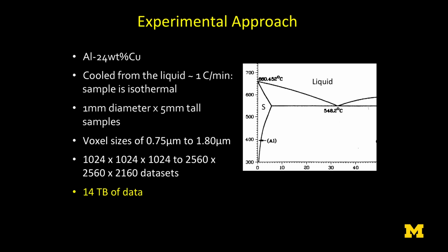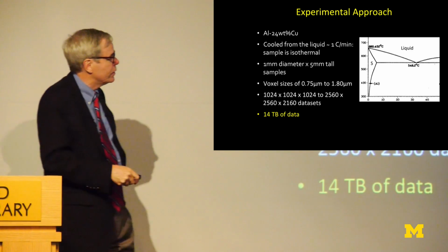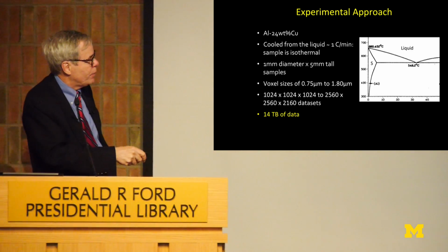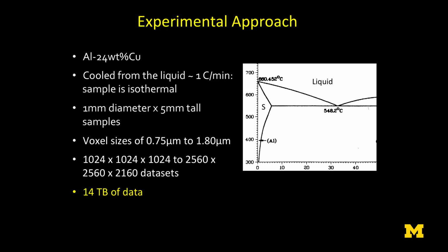So here's the experiment. We start with a liquid up here, solid over here, solid down here. This is a solid-liquid region in here. This is sometimes called a mushy zone, where you have mixtures of solid and liquid. You want to think about this as a slush, this is a liquid, and that's the snow. So you cool down from high temperature, and we're going to watch the dendrites form as you get below this line of the liquidus temperature, and you're in this 2-phase field.